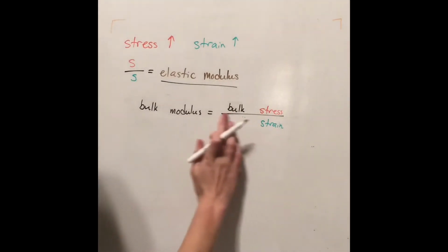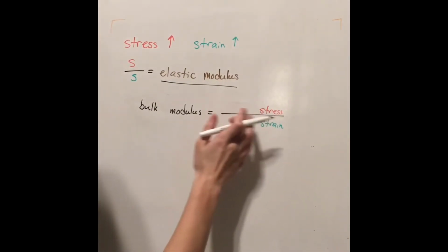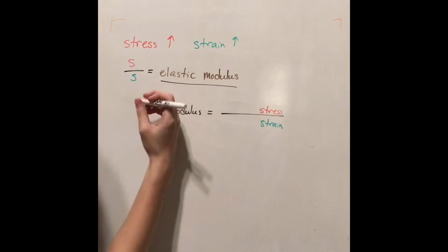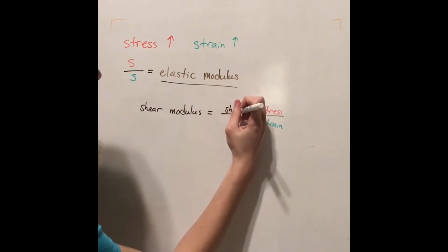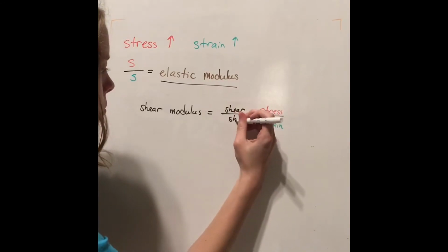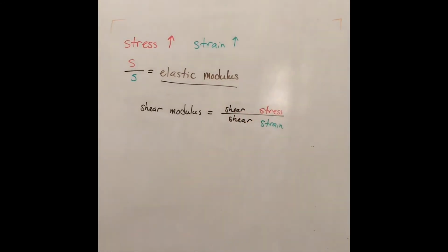The elastic modulus that corresponds with shear stress and strain is referred to as the shear modulus, which measures the ability of a material to resist transverse deformations and is only a valid indication for small deformations, after which the material is able to return to its original form. Because materials with larger transverse deformations lead to permanent fracture, it cannot be measured using the shear modulus. The shear modulus can be calculated using the equation shear modulus is equal to shear stress divided by shear strain.